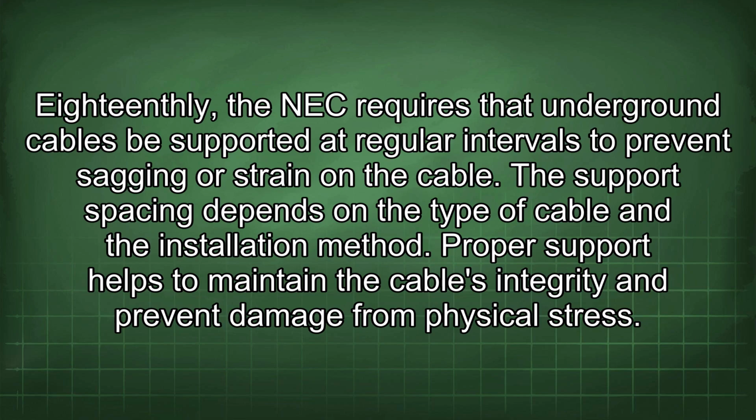18thly, the NEC requires that underground cables be supported at regular intervals to prevent sagging or strain on the cable. The support spacing depends on the type of cable and the installation method. Proper support helps to maintain the cable's integrity and prevent damage from physical stress.